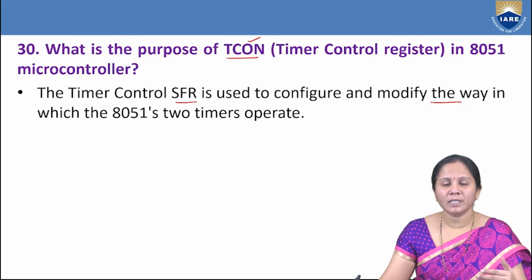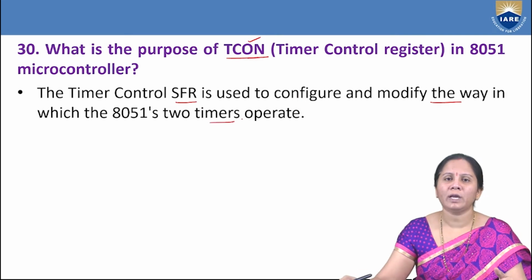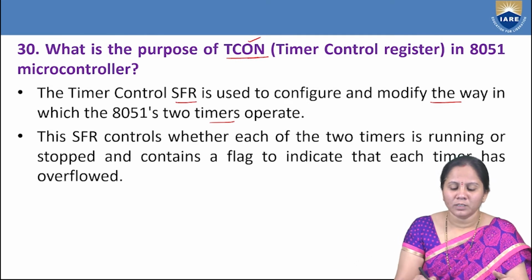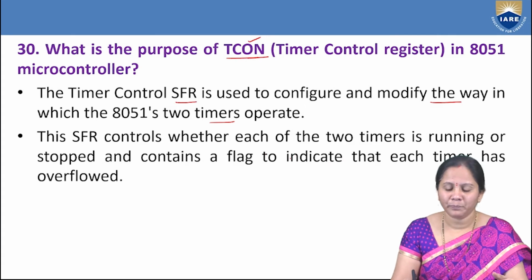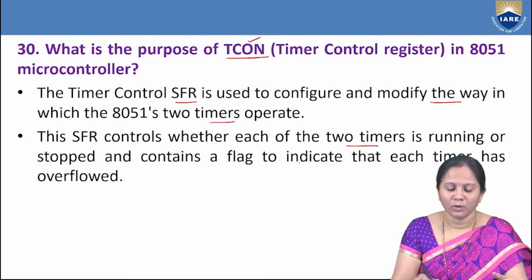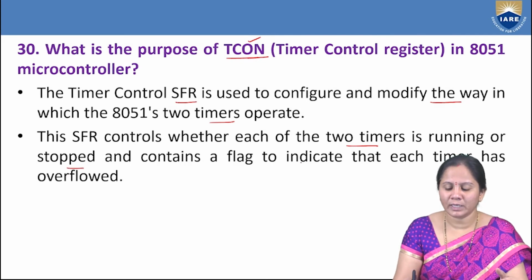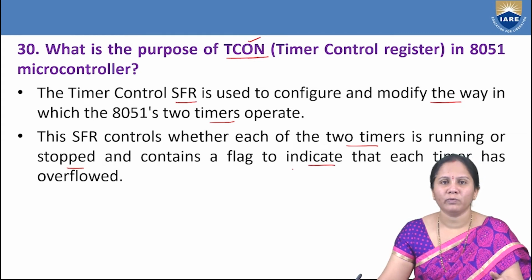It consists of two timers, so the TCON register is related to the 8051's two timers' operation. It controls whether each of the two timers is running or stopped, and it also contains a flag to indicate that each timer has overflowed.